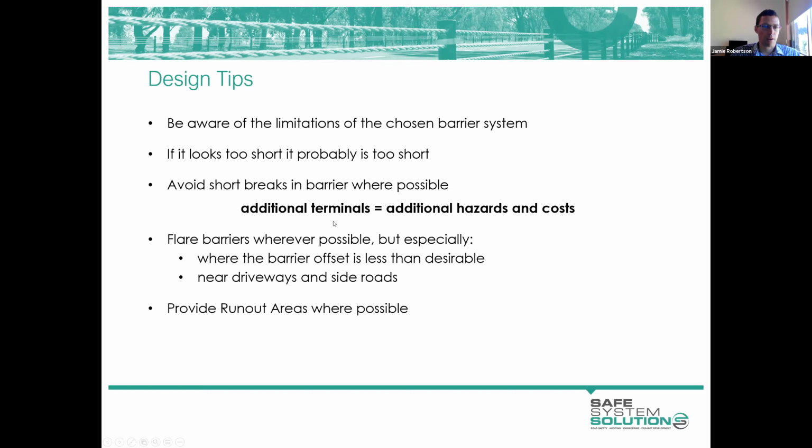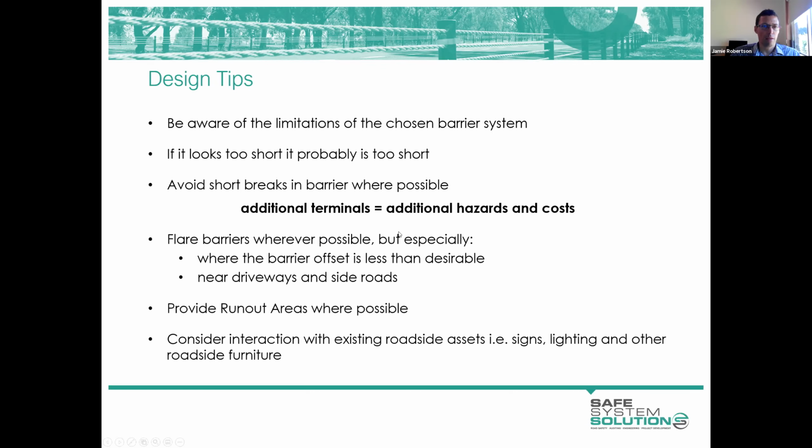Think about providing run out areas wherever you can. And think about all of those things at the roadside that the barrier needs to integrate with. I can't stress enough how important an initial site visit is when you're thinking about a barrier treatment. Get out there, take all the photos you can, do a Dial Before You Dig, understand what you need to work with and around out on site. There are things that might need to be relocated, reinstated, that will influence the location of your barrier and how you go about designing it.